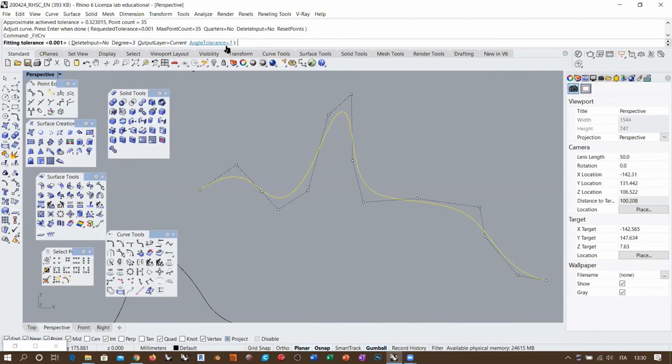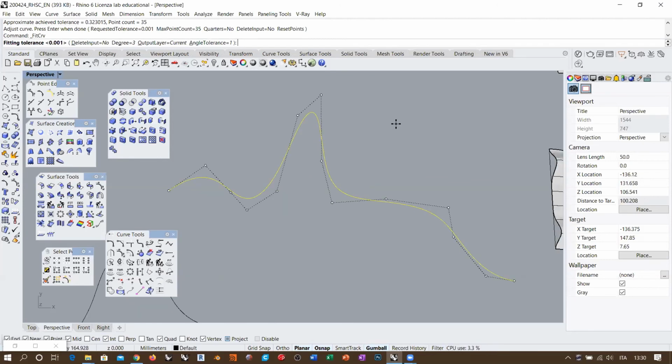So in this case, you lack some information. You have no control over the control points, so the risk is that you get a completely different topology. Remember that the amount of control points is also important because it determines the amount of knots and the amount of spans.